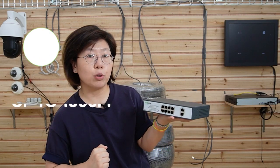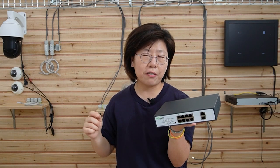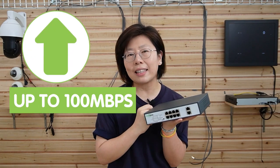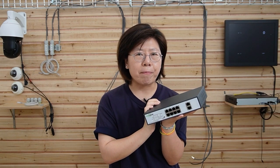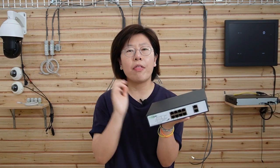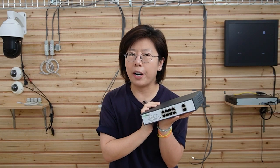It can reach up to 1,600 feet, which is more than enough for all the cameras. And also it can provide high speed. The connected device can receive up to 100 megabits per second, which meets the 4K IP stable video stream. It is compatible with the IEEE 802.3 af, at, and bt standards. And each port can provide up to 30 watts of power.